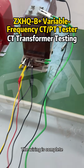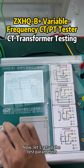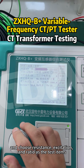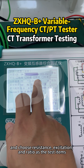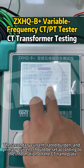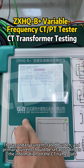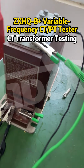The wiring is complete. Now, let's set up the test parameters. First, select CT as the test type, and choose resistance, excitation, and ratio as the test items. The current temperature is 25 degrees Celsius. The secondary current, rated burden, and primary current should be set according to the information on the CT nameplate. Let's check the nameplate.